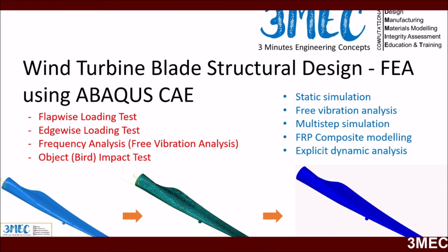What I have done is remove all the internal structures to reduce the simulation time, so there is no structural support available inside the blade. If you are familiar with blade architecture or cross section, you can have a lot of structural features inside, such as stiffeners and spars. I have removed those, and that's why all our results will be very low, because we only have a composite skin, which is more for aerodynamic performance rather than structural performance, right?